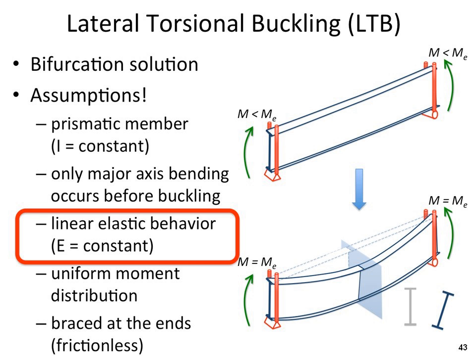We have a couple questions back on the torsion stuff. I didn't want to get too far. If we could just cover a couple of them. First of all, the AISC Design Guide 9 on torsional analysis, do they define these warping coefficients, and do they give more values on these? Yeah, in fact, even in the front of the AISC manual, you've got the cross-sectional area, the moment of inertia about each axis. Sitting all the way to the right is the St. Venant J constant and also the C sub W warping coefficient.